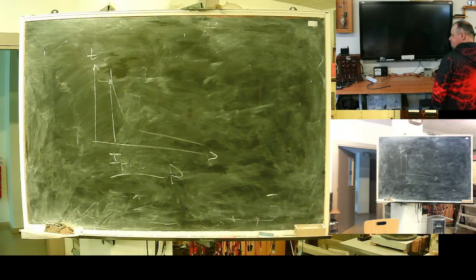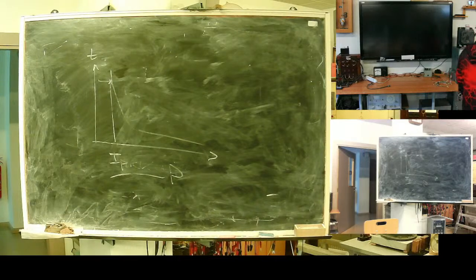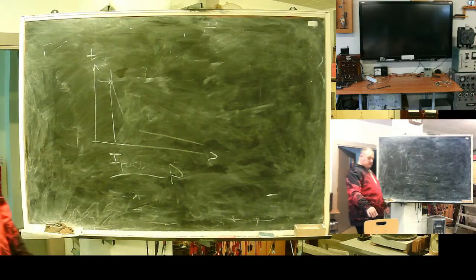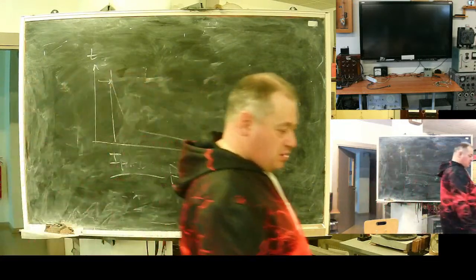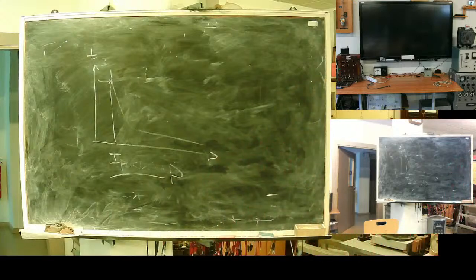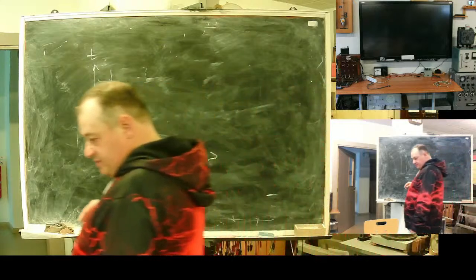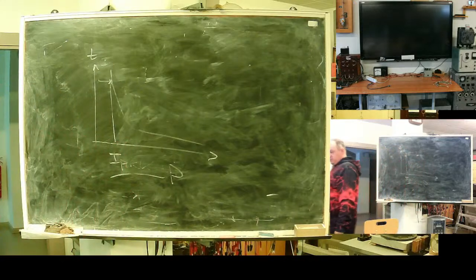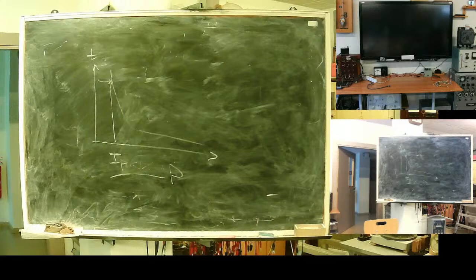What did I forget? I named characteristics. So the key idea: when you create a protection for a distribution network, it is better to make it multi-stage, with the last stage coordinating well with fuses and thermal relay equipment, low voltage circuit breakers.